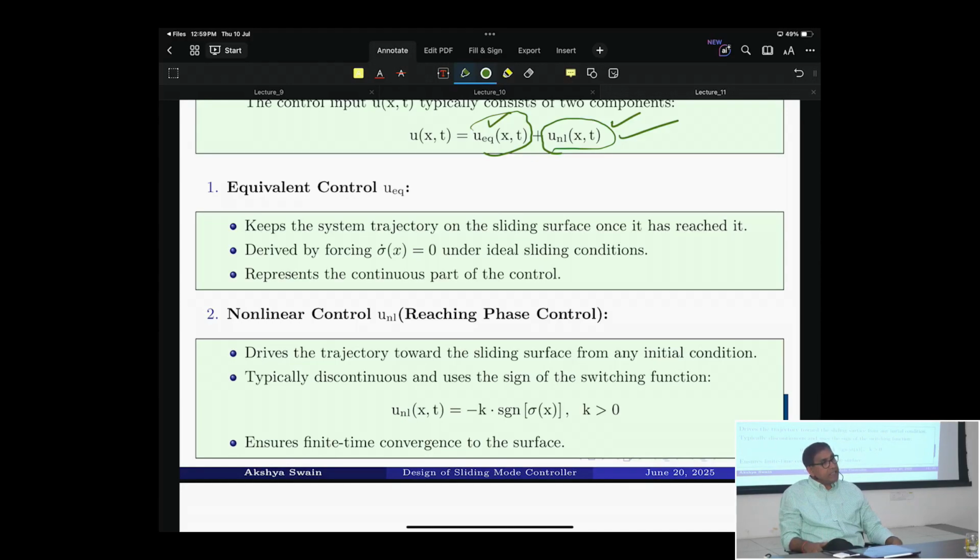in signal processing, in filtering, we have been taught if there is a noise signal, you design a filter, it will filter it out. That's clear. Obviously, no problem. If the signal bandwidth and the noise bandwidth are separate, then you can use a filter. But if they overlap, then by filtering the noise, you also filter the signal, which is not desirable, right? So these type of things, normally what we do in power electronics, those people who are working in power electronics, they know.